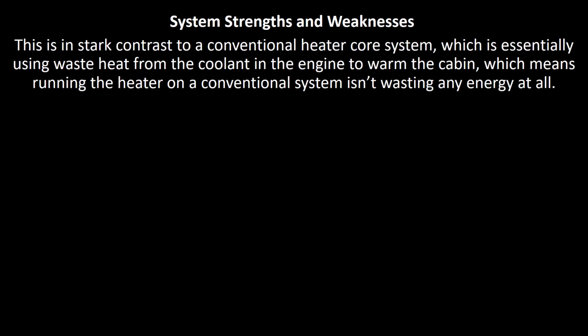This is in stark contrast to a conventional heater core system, which is essentially using waste heat from the coolant in the engine to warm the cabin, which means that running the heater on a conventional system isn't wasting any energy at all versus the electrical system, which is going to be taxed by the use of a PTC heater.